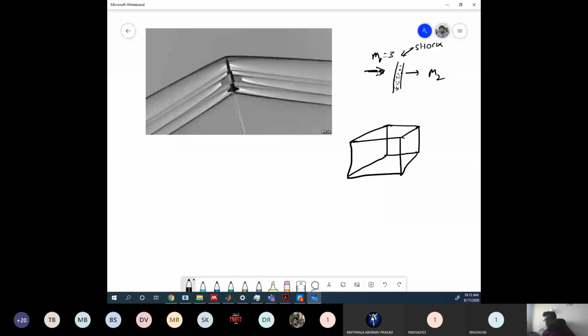But since here in this high-speed aerodynamics, as I said, we need very simple empirical relations, we'll have to derive a simple equation. Let's say you have some wedge like this instead of an aircraft. So this is a shock wave around an aircraft. I take a simple wedge, and you have some M infinity equal to 3. Obviously this wedge will have some certain angle theta. For that angle, since the flow is moving at very high supersonic speeds, you will generate some shock wave, which will be of some beta.